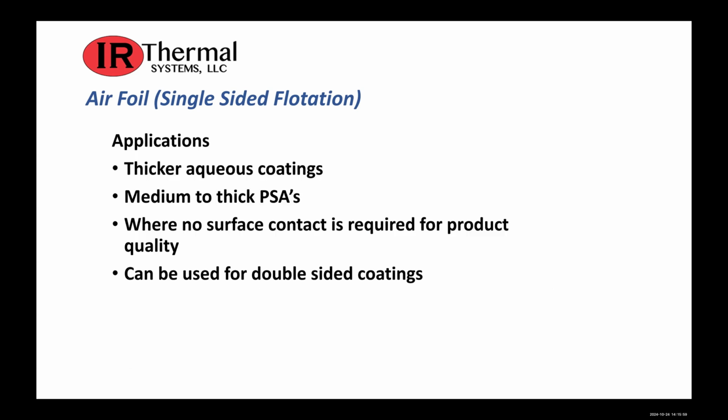The common uses for this type of nozzle would be on thicker aqueous coatings, medium to thick PSAs, and where no surface contact is required for product quality. That might be an optical film application or a very special tape. And since it is a non-contact web support, it can be used on double-sided coatings